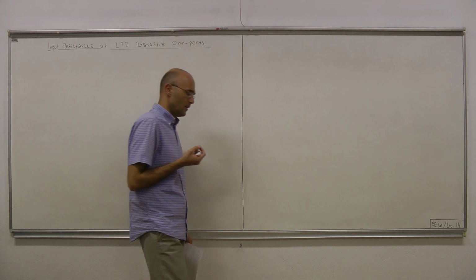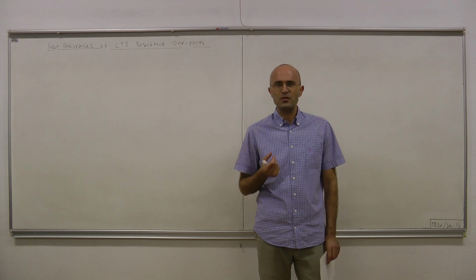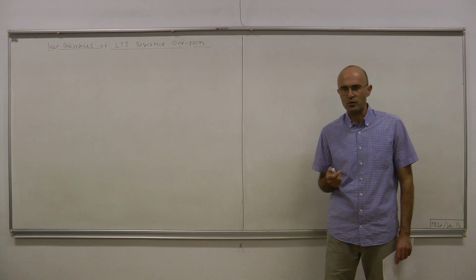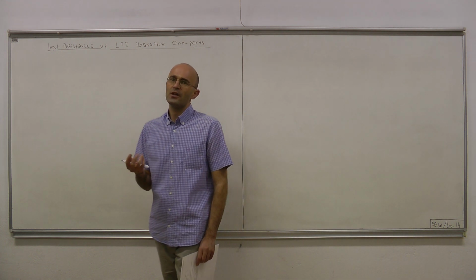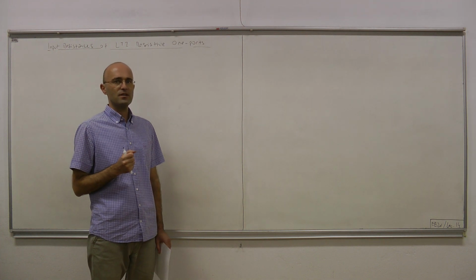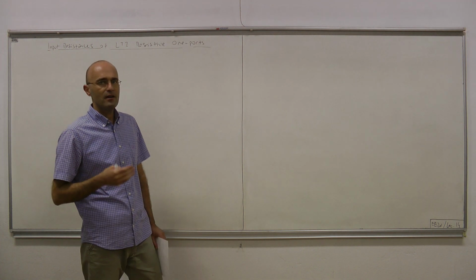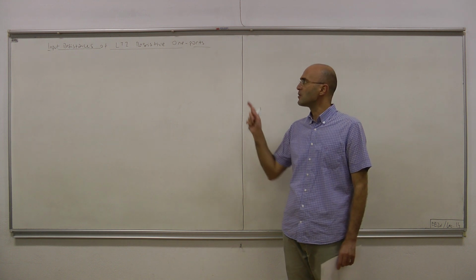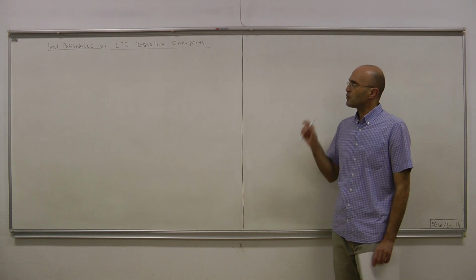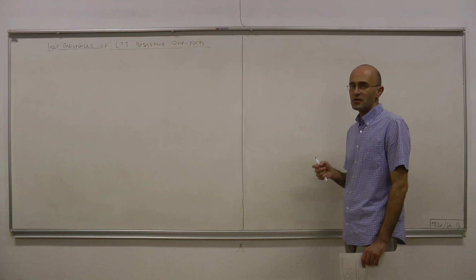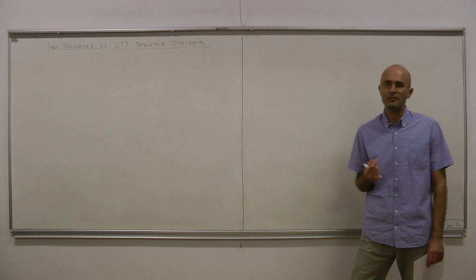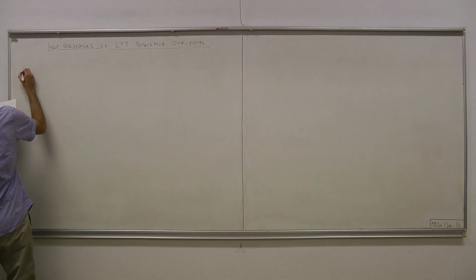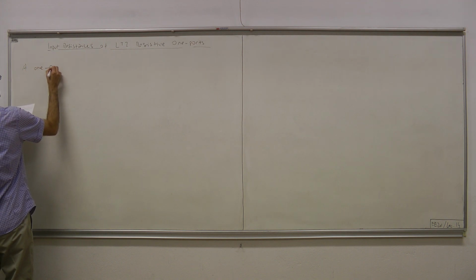If you have an LTI resistive one-port circuit that contains only LTI resistors, LTI dependent sources, and ideal transformers, then it turns out that that one-port circuit can be represented by a single equivalent component, and that component is an LTI resistor. And now we will try to figure out how the resistance of that equivalent resistor can be calculated. So here is what we're going to do: